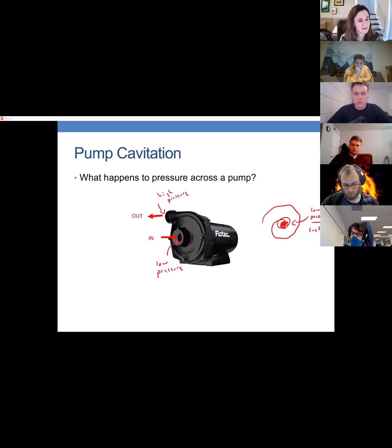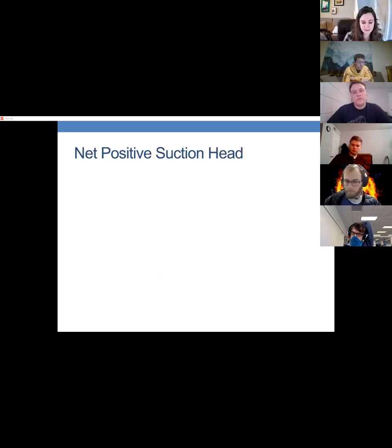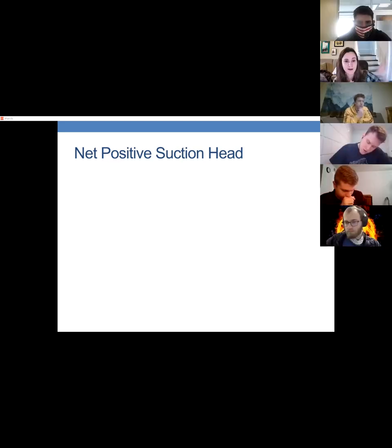It could even stagnate inside of there. What that means is that even if there's no cavitation in the pipe, there could be cavitation inside the pump. That's what we're establishing there. So how do we prevent cavitation? Through a concept called the net positive suction head.